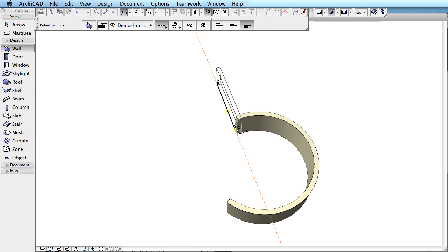After creating a wall along the main Y direction in 3D, let's continue and create another wall segment, which is tangential to the circle segment. Here we will need some additional temporary guidelines. We can create a circular temporary guideline by moving the mouse over the existing outer perimeter of the circular wall in 3D. Please note that there is an orange dot on the guideline.